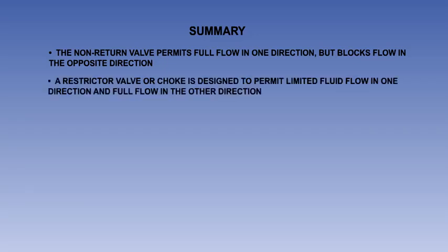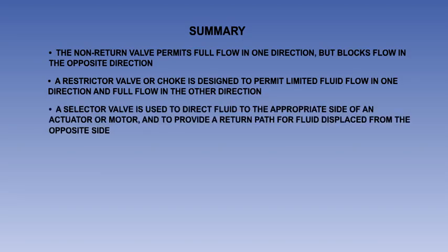A restrictor valve or choke is designed to permit limited fluid flow in one direction and full flow in the other direction. A selector valve is used to direct fluid to the appropriate side of an actuator or motor and to provide a return path for fluid displaced from the opposite side.